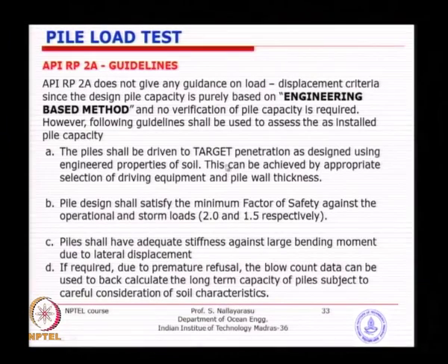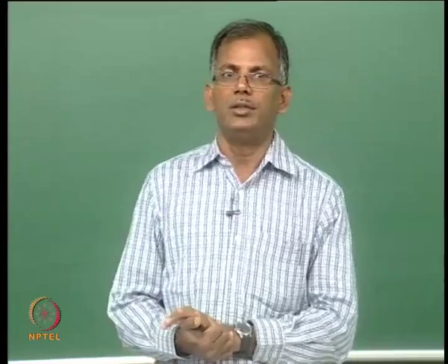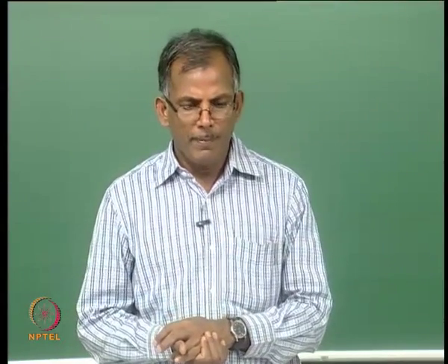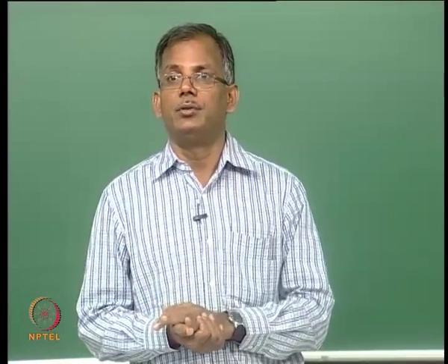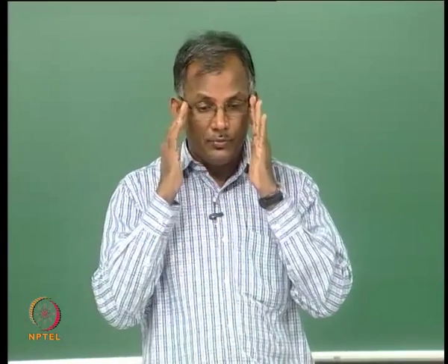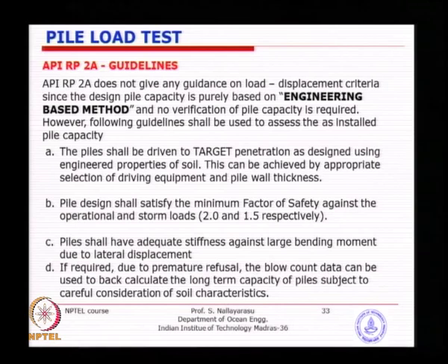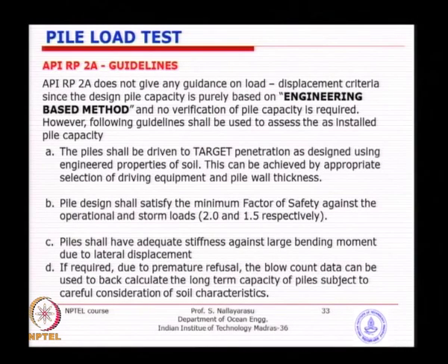What the API says, we do not have a procedure to restrict the displacements. Unfortunately, there is no requirement, because we do not need it, because offshore structures are subjected to so much higher loading that if you restrict 25 mm displacement, for example, your structure will be so much bigger and may not be practical.